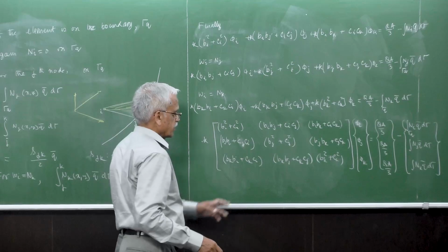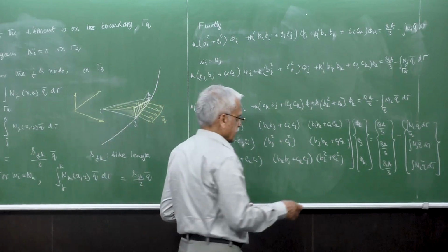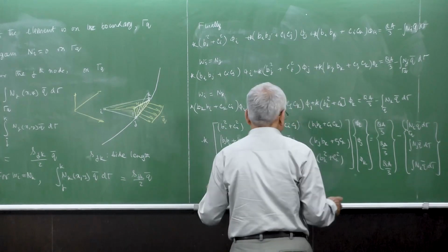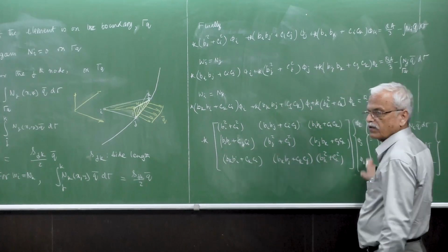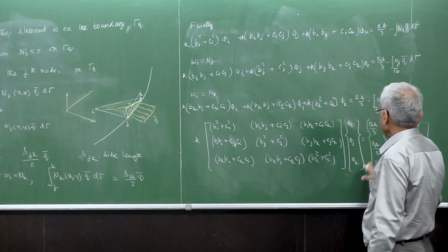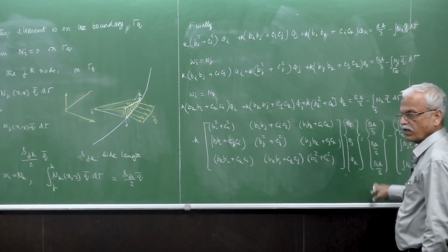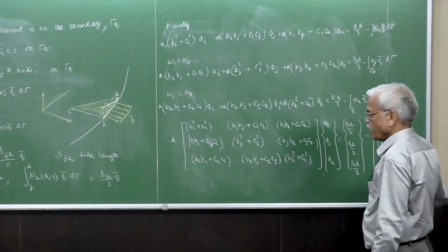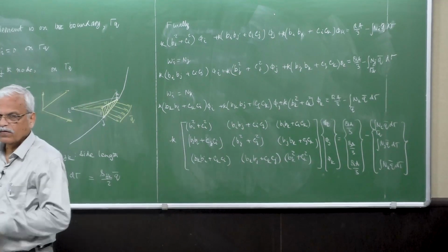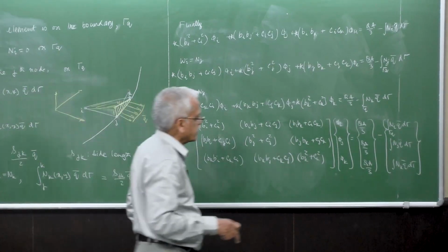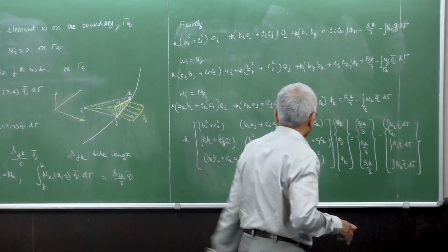Where this is the matrix, we used to call it the K matrix by itself. And please don't get confused with this K. And then multiplying these are the temperatures, phi I, phi j, phi k. And this is the heat source term. And this one you have to accordingly include if any of the element edges are falling on gamma Q.